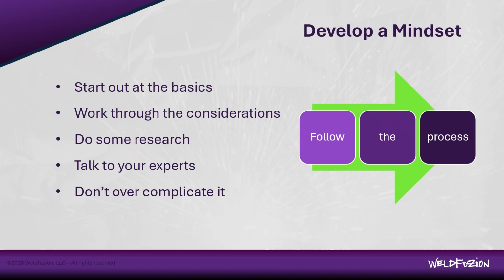But let's walk through this. Okay, start with the basics. Understand the code, the material, the application so that you can dig into it. Consider the key elements like what, where, when, how, and even who is going to do this welding. And then do some research. Look at allowable processes.